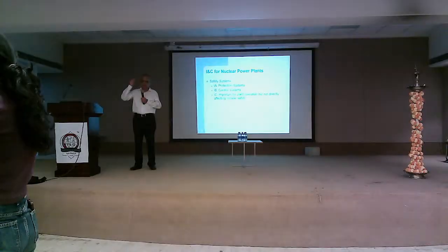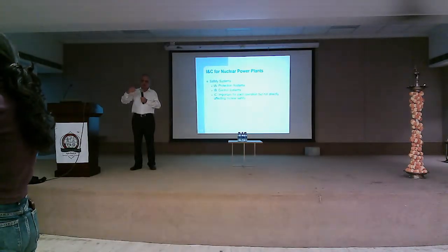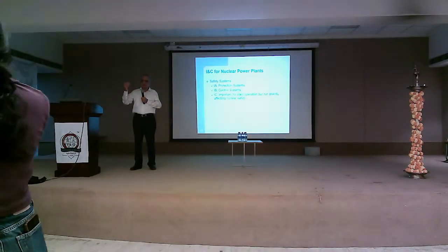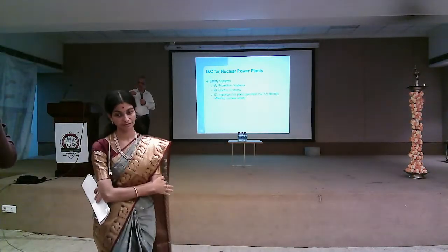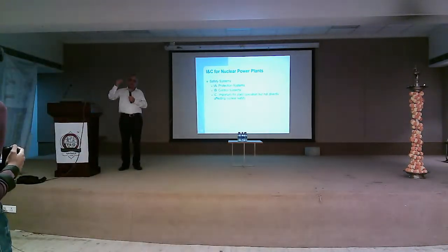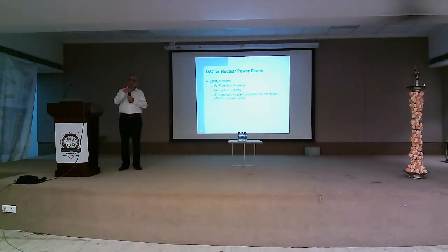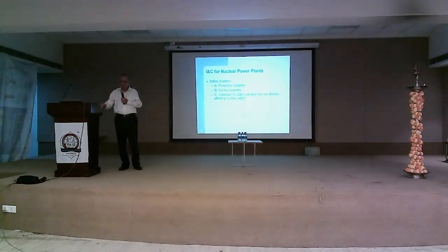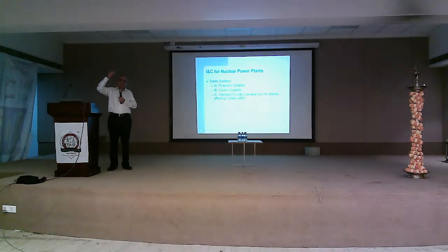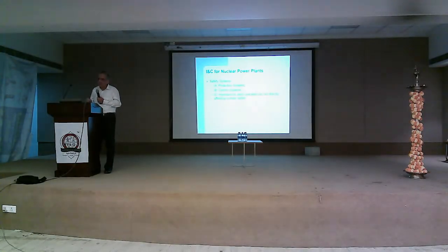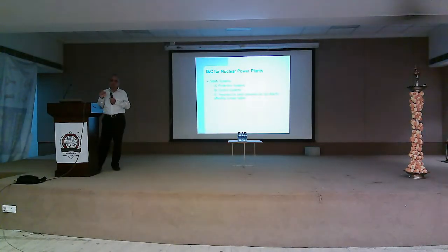If you remove the neutron absorbing rods, neutrons will increase, so power will increase. When you put them back, power will reduce. Somewhere we have to move the control rod so that it remains the same and power is maintained. That is how you control. Similarly, when the shut off rod falls, it is neutron absorbing material. It will absorb neutrons and bring down the power. That is one protection system.